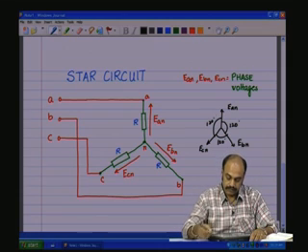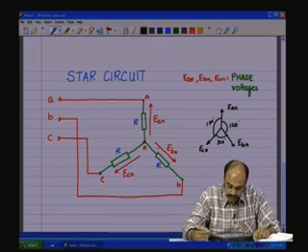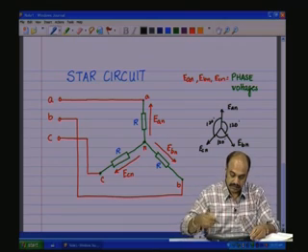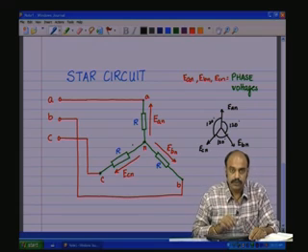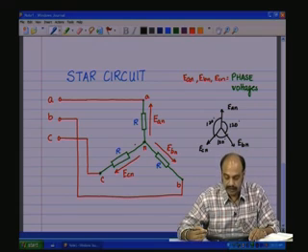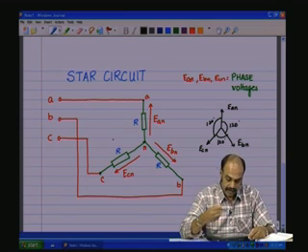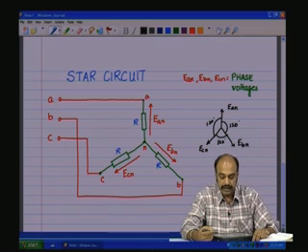A and C. So, as the phasor diagram is in the shape of the star, superposing the circuit on that, you get the circuit in the shape of a star, but in actuality it is the phasors which are 120 degrees displaced with each other, but the circuits can be written in any other shape also with all one ends joined together. But however, for clarity and aesthetically pleasing look, this is a much more descriptive way of writing the circuit.